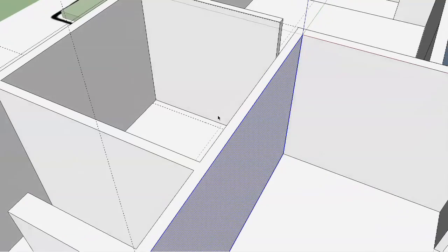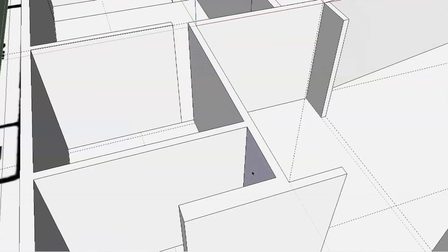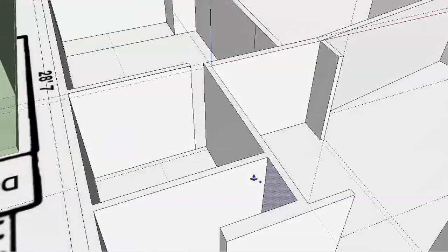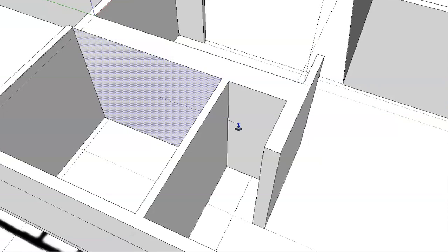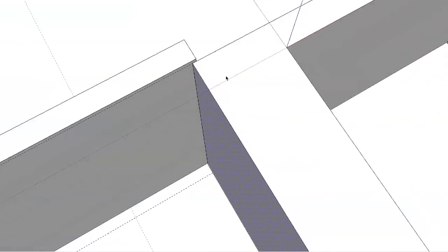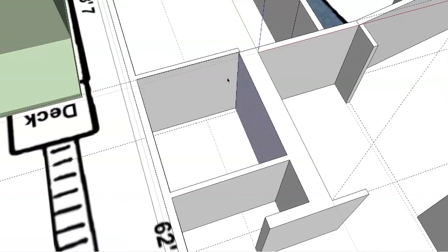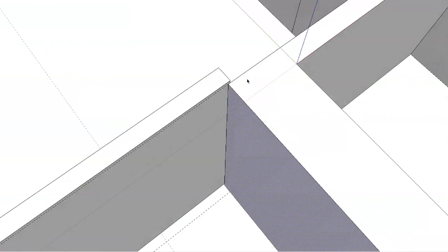So this wall here actually needs to be thicker than it is right now to accommodate all those appliances. So what we're going to do is use our push-pull tool, and pull these chunks of wall back out about 1 foot. So we're going to add about 1 foot of thickness to it, like that. There we go. Perfect. And you can see when we do that, this is another instance of things just kind of starting to click together and fall into place. It lines up almost perfectly with this other wall that we drew right here. It's meant to be, clearly. So let's go ahead and fix this wall as well. Now, the first thing you'll notice is it's about 1/2 inch maybe too long.